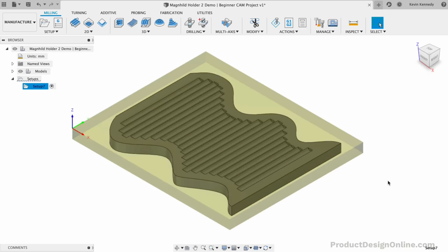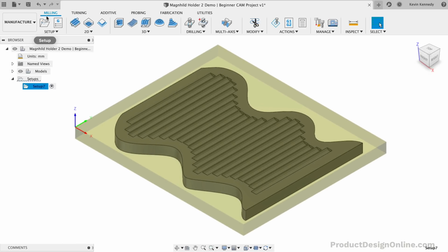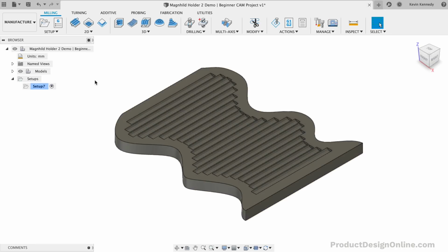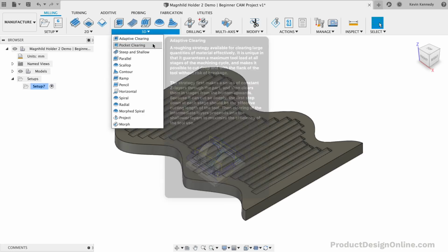We're now ready to create our first toolpath to mill the inside cavities. You'll see while we're in the Milling tab that Fusion divides features up into different categories. Let's start by carving out this 3D cavity where the pipes rest. We'll need to use a 3D path since the geometry is 3-dimensional.